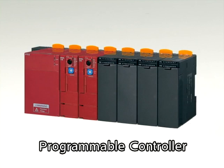Moreover, in some cases, only the program has to be rewritten, even when the controlling method has been changed, eliminating the need to change the wiring. As such, the programmable controller is the choice for complicated sequence control. The programmable controller is also referred to as a programmable logic controller, PLC, programmable relay, or simply sequencer.